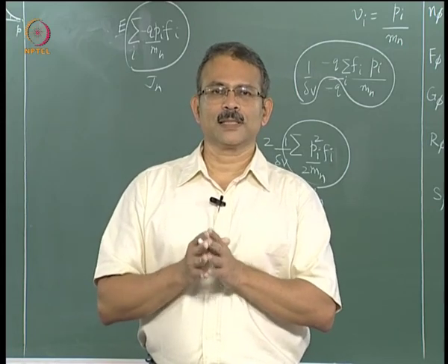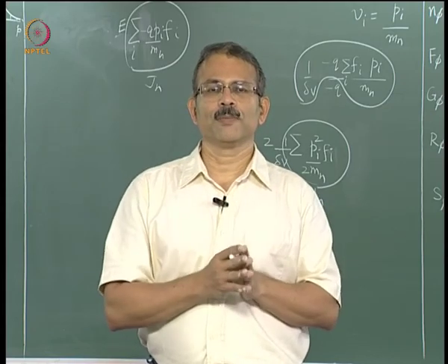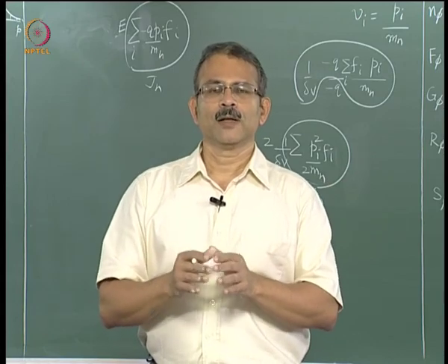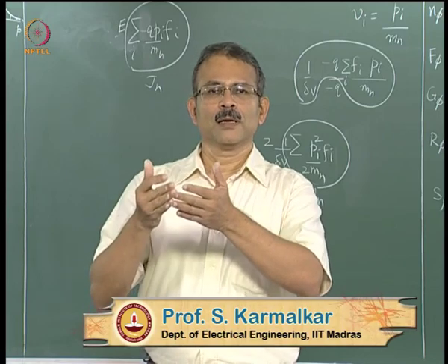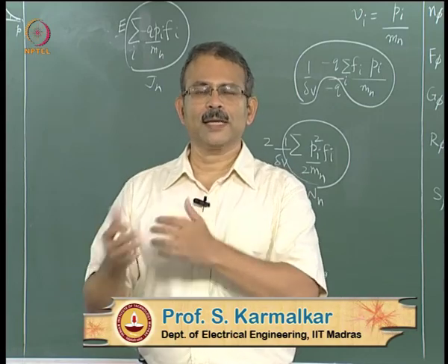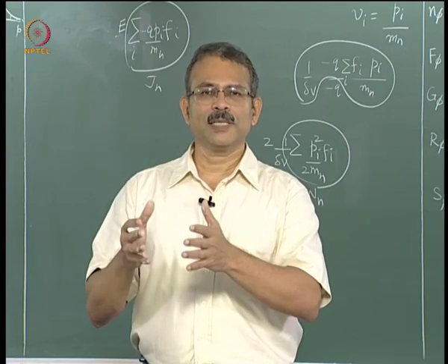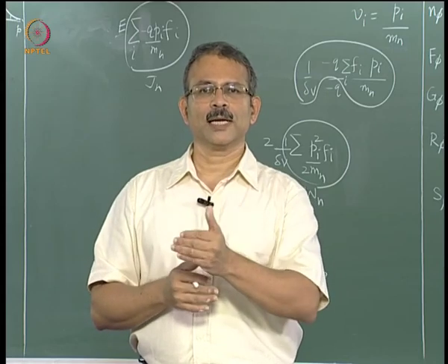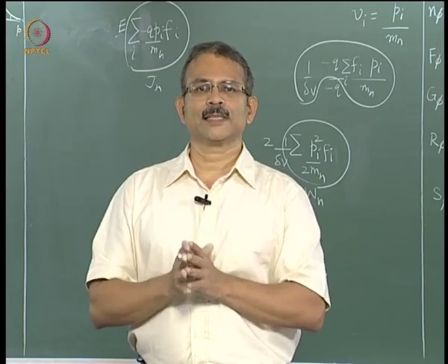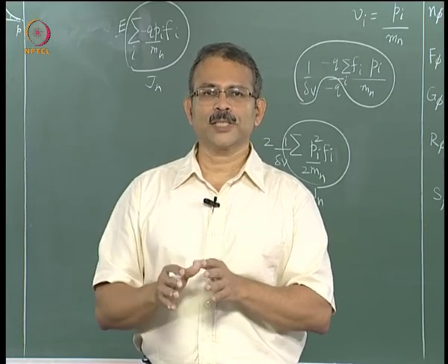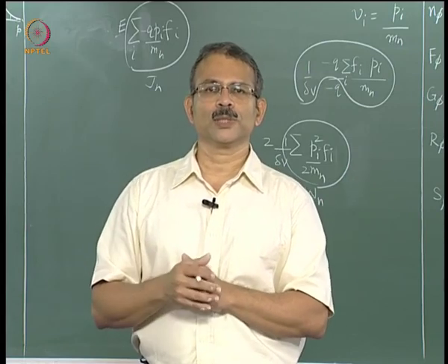The second approach that we discussed in today's lecture avoided solving for f because it is a function of 7 variables. Instead, we modified the Boltzmann transport equation into balance equations for quantities which are of direct interest to us, namely the carrier concentration, the current density, and so on. We derived these equations for carrier concentration, current density, and kinetic energy density, and we call these equations the balance equations. In the next lecture, we will see how these equations can be applied to explain velocity saturation, velocity overshoot, and all these phenomena.